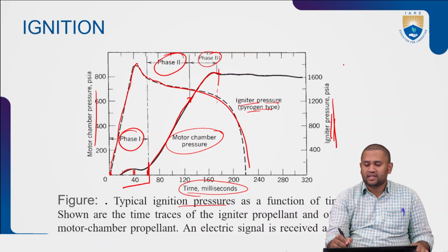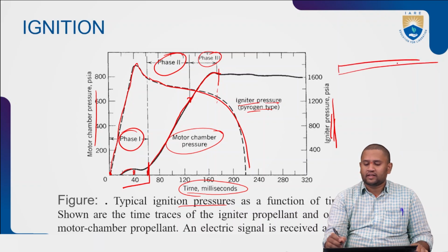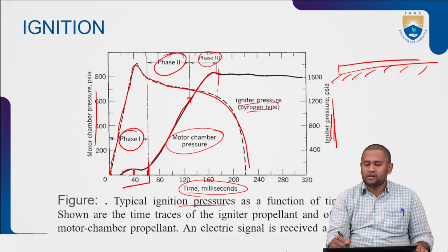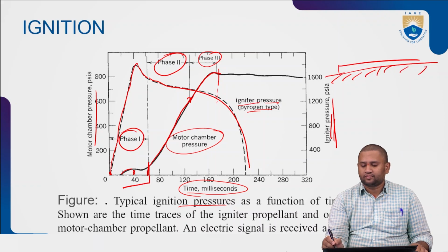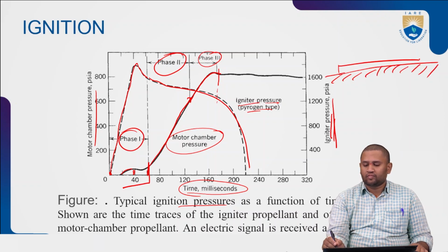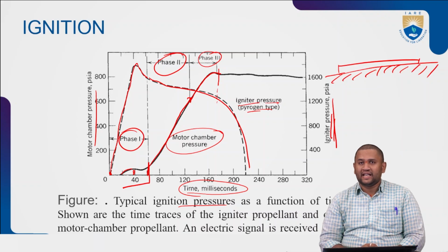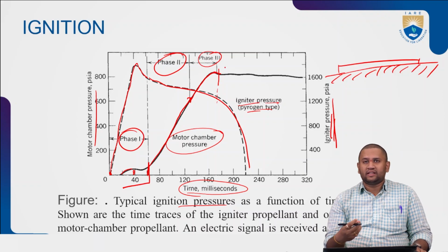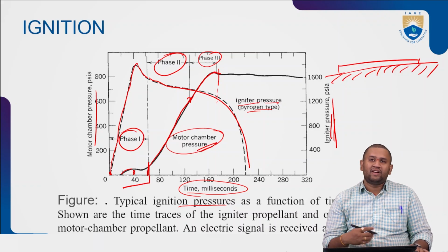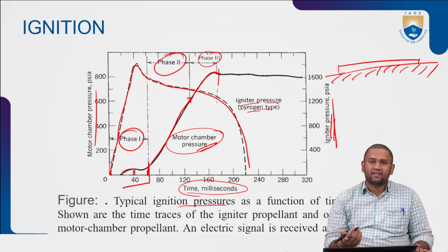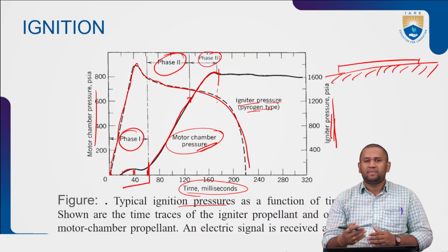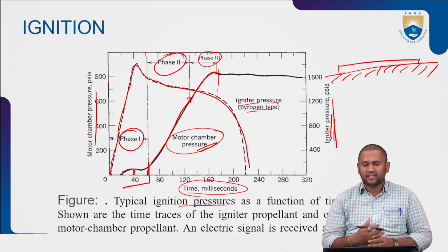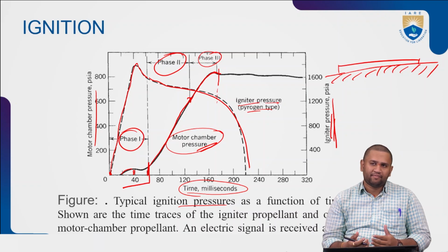So, based on my grain design, particularly the grain shape or structure, the pressure inside the motor chamber will tend to attain its equilibrium, meaning there will be minimal pressure differential between two subsequent seconds or two subsequent time frames.